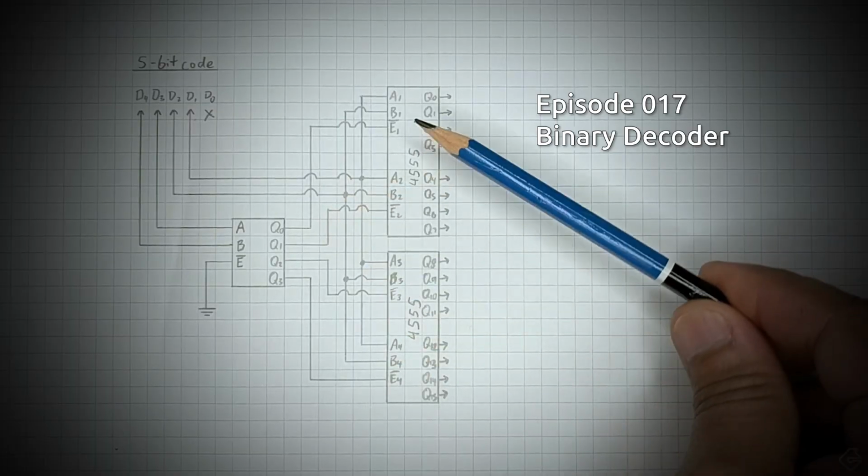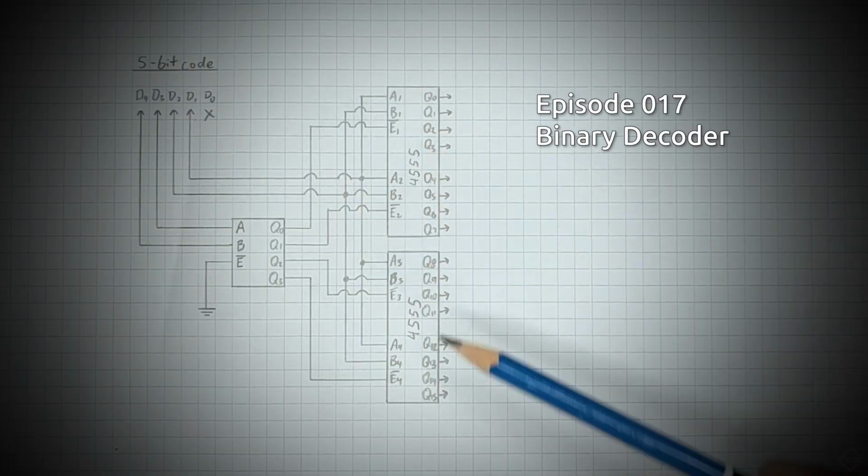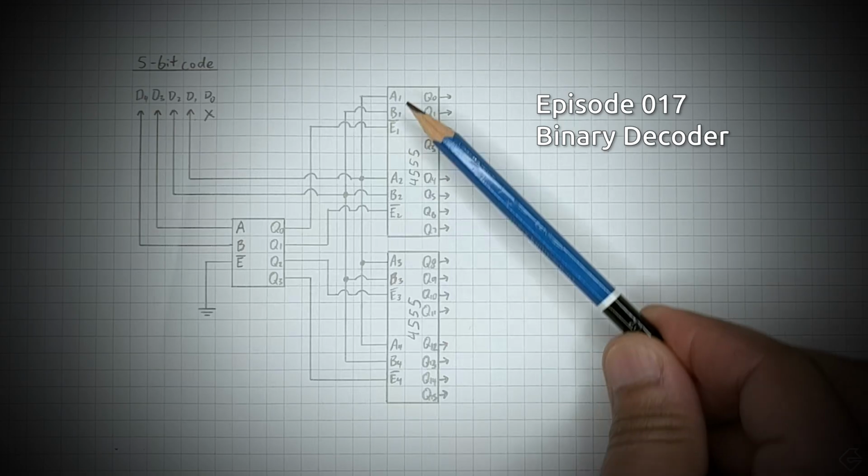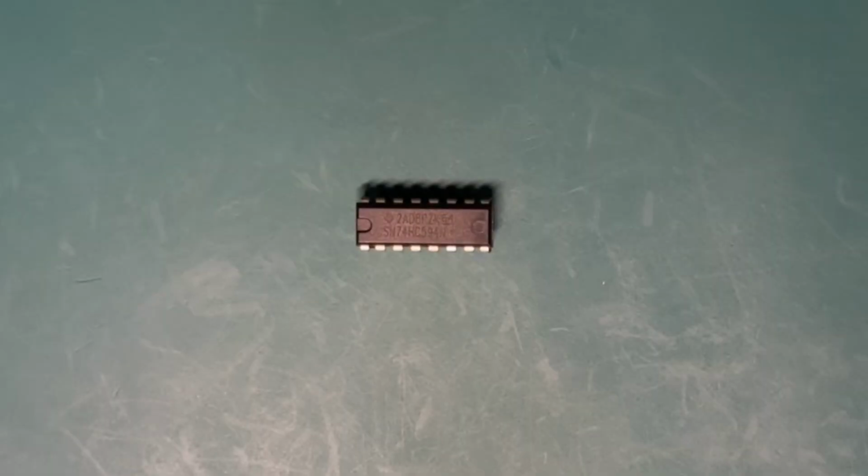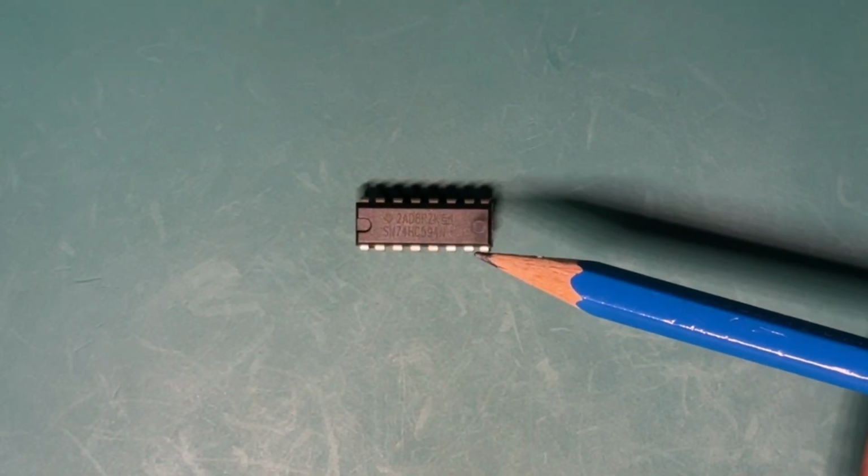Our problem, of course, is that with the 6 LEDs that we currently have connected to our PIC microcontroller, it's out of pins. A number of episodes ago, we designed this system with at least 16 discrete levels of intensity, and we need at least 16 indicator LEDs in order for us to know what intensity level it is. And that's why I wanted to use this 594 shift register.